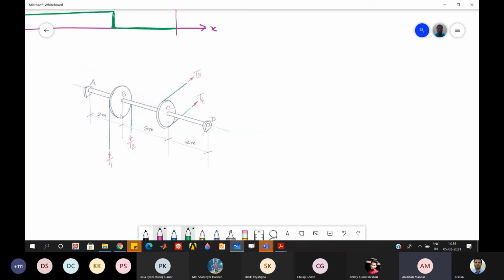Sir, first, it was given that T1 is equal to 2T2 and T3 is equal to 2T4, and the T1 value was given. From that I calculated the amount of torque which I should replace on the given rod. Then I did the same for T3 and T4. In the last video you showed the same type of problem, and using the same concept, that the torques have to be equal and opposite, I calculated the moment and then made the twisting moment diagram.